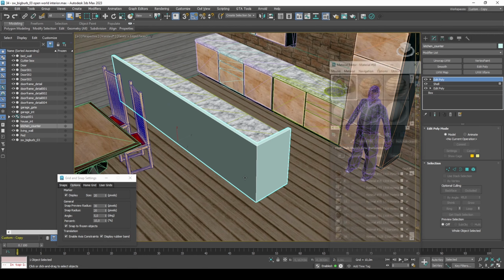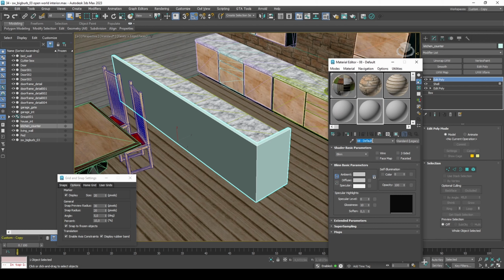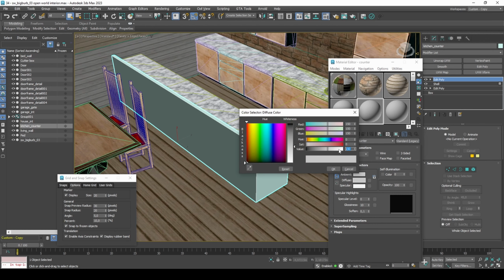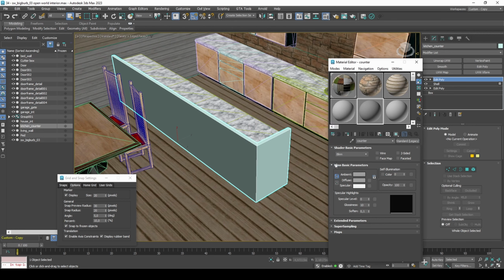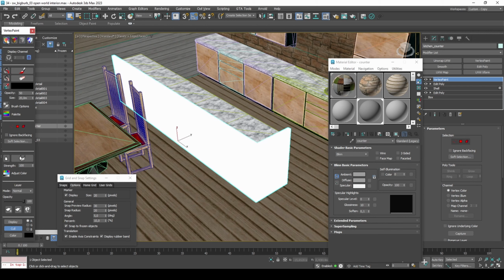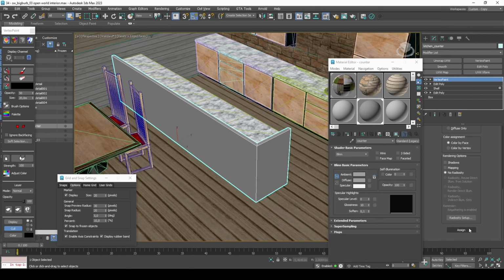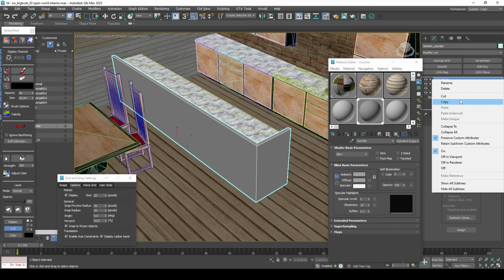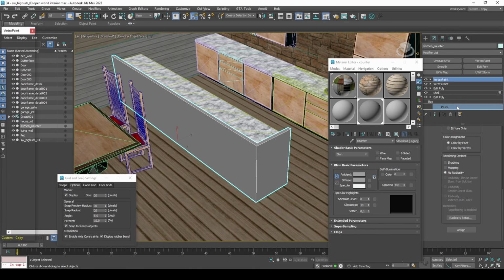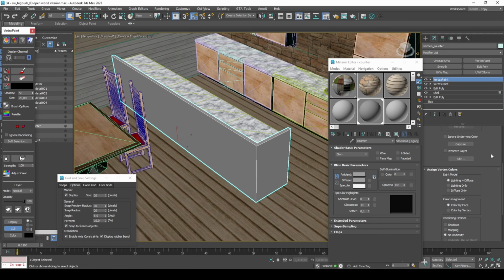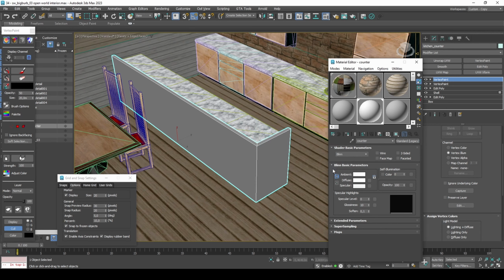Select the cover of the kitchen counter and apply a gray standard material. Change the color value to 90. Bake scene shading into vertex colors, and copy-paste the modifier and change to vertex illumination in the second modifier. Change the material color to white and attach to the interior.